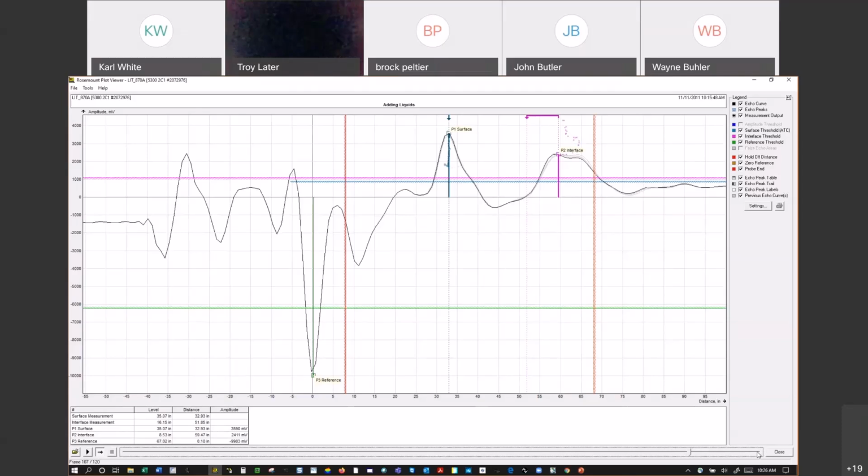And let's wait until the amplitude comes back up as this separates. So you can shut off the pump, let it separate in here, and we actually put logic in the program to where if it gets below about 4,000, we stop the transfer pump. And you can wait till it gets above 5,000 before you turn it back on. So that way we're not ever pushing emulsion into the oil tank, right? We know we have a good oil-water interface.